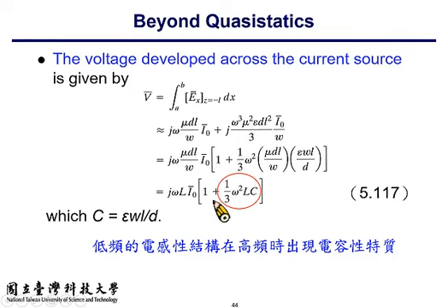the integrated result should be different, because as you can see in the previous slide, the electrical field is not homogeneous. It's a function of position Z. So the total voltage developed at different positions are not the same. And here we look at the voltage at the left end. So you substitute Z with minus L into the expression to get its first term and the second term.